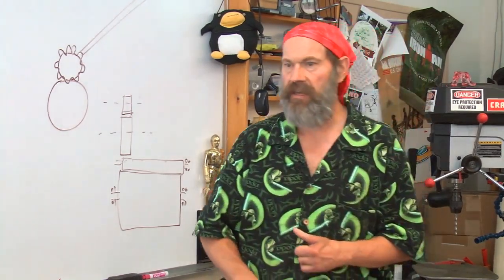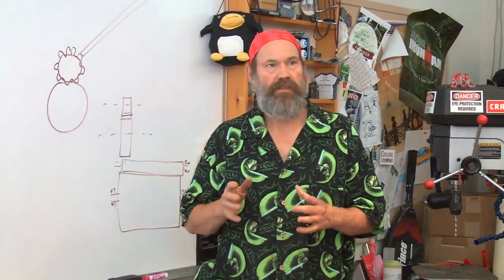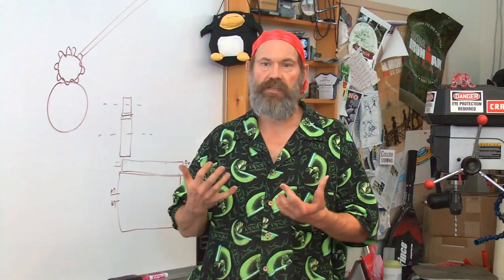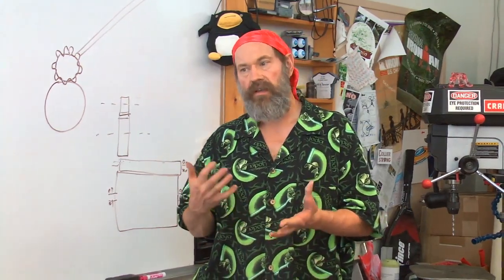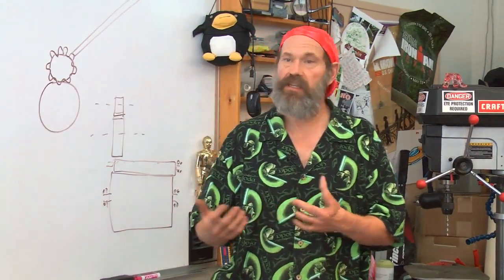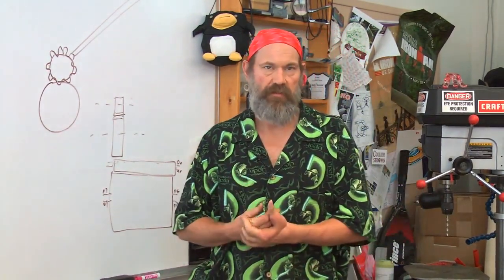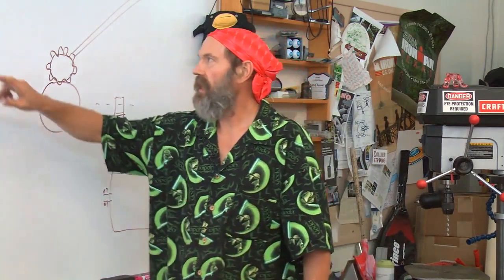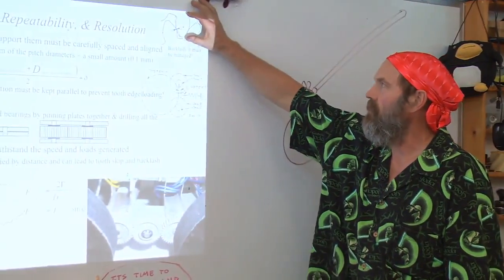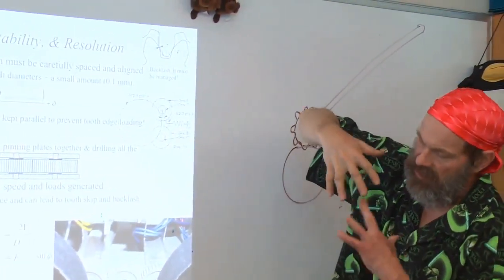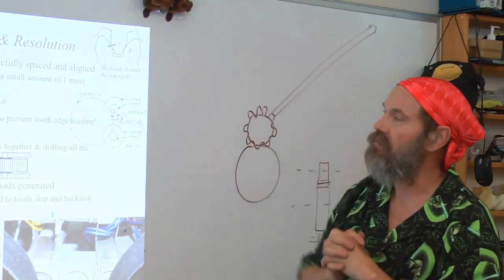Planetary gears, on the other hand, are much harder to design with no backlash, so they use very high precision components and design it with minimal backlash. When you buy a gearbox, be aware of what the backlash is and what is acceptable or not. If you're designing and building your own, it's fairly straightforward to do the calculations in terms of how much gap you need to accommodate the center distance errors that you may have just by manufacturing or by thermal expansion.